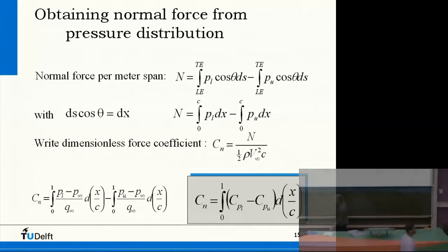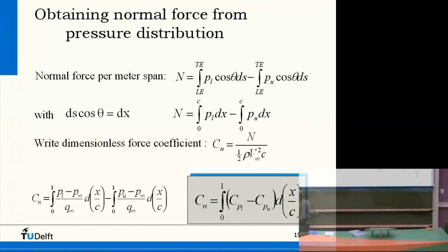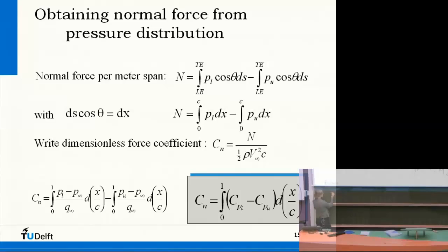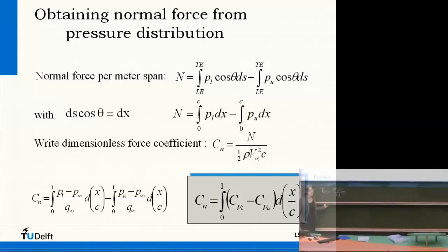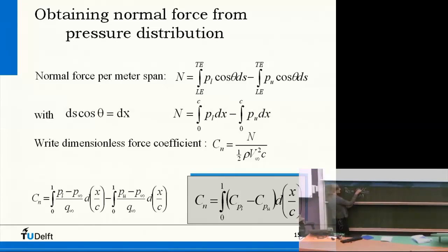So the last lecture. So what is it and how is it used? Reynolds number is rho V L over mu. Rho, density, V, speed, L, a typical length. So this is Reynolds L then at the location L. This is convection phenomena. Flow speed related. Below it's the viscosity coefficient, so this is diffusive viscosity.